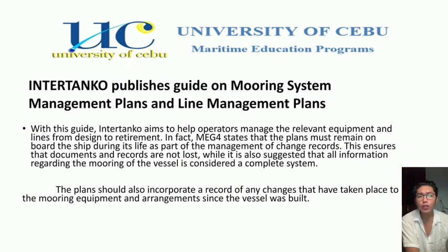It is also suggested that all information regarding the mooring of the vessel is considered a complete system. The plans should also incorporate a record of any changes that have taken place to the mooring equipment and arrangements since the vessel was built.